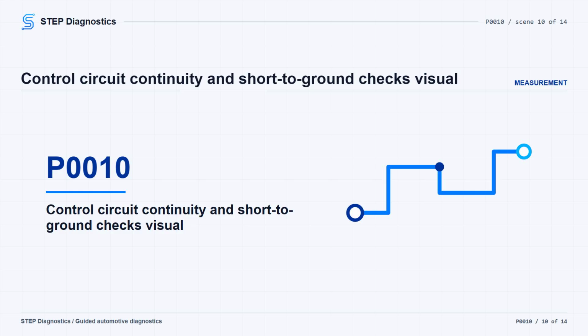If it is infinite resistance, test the control circuit end-to-end from the component harness to the control module harness. That circuit should be less than 2 ohms. If it is 2 ohms or greater, repair the open or high resistance. If it is less than 2 ohms and the circuit checks pass, the supported path points to the engine control module.